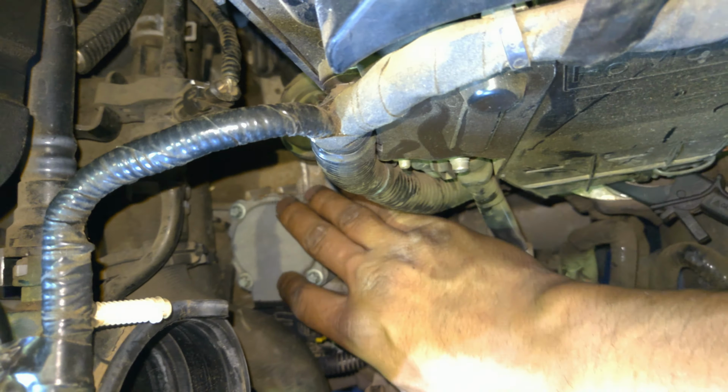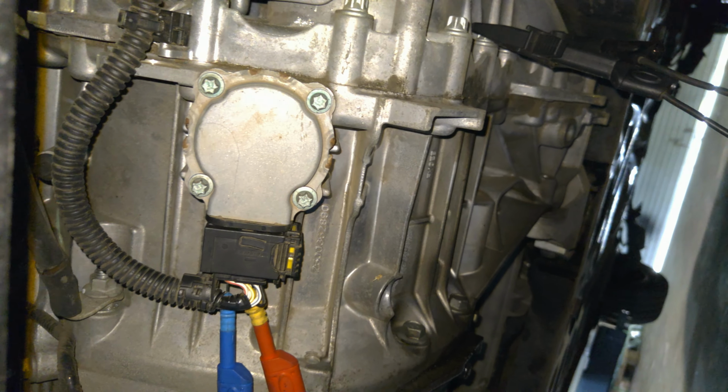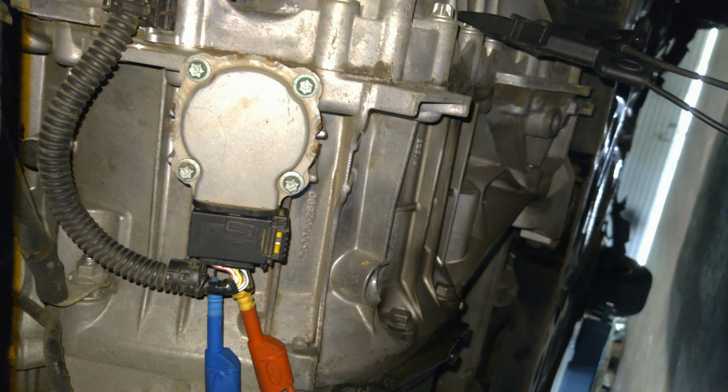And the other one is down. You have to go underneath the car, right at the front on the side of the gearbox. That's where it is. Exactly the same part. You can swap it around and see if it does anything different. That's what I'm going to do. In fact, I've already done it. So I've already swapped A to B, and we're going to start the car and see if there's any difference.